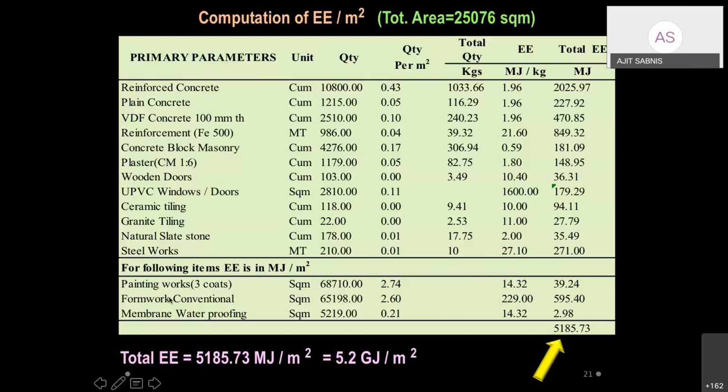And also now in the inventories, or where the data are available, there are certain inventories where embodied energy is expressed in terms of square meters, for example, megajoules per square meter. Otherwise, in the majority of the items, the embodied energy value is given in megajoules per kg.